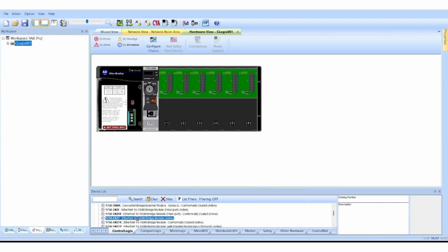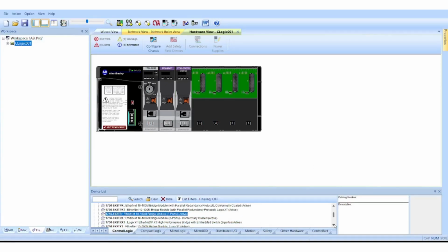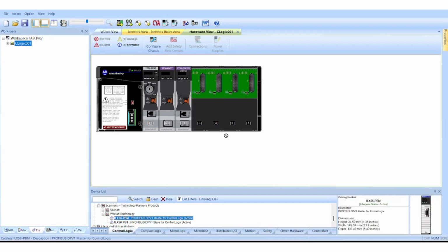This provides several advantages. The processing load is distributed. The PLC programs can be organized according to process areas. Troubleshooting becomes easier, future expansion becomes more manageable, and a problem associated with one controller does not necessarily have to affect every other process area in the same way. This is particularly useful in a large continuous process application.